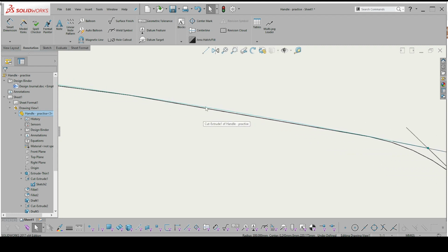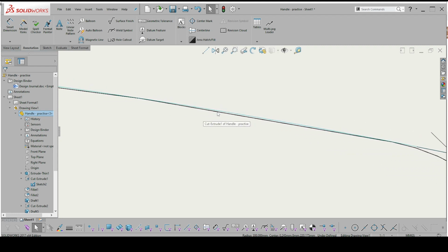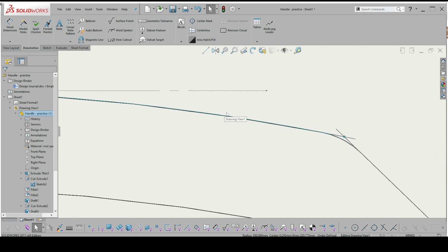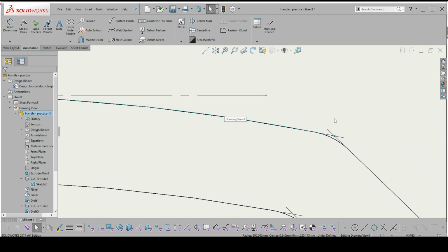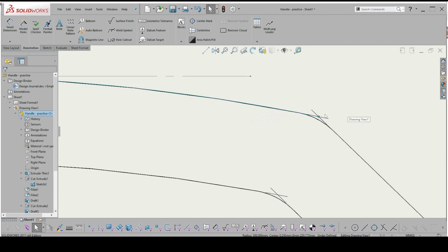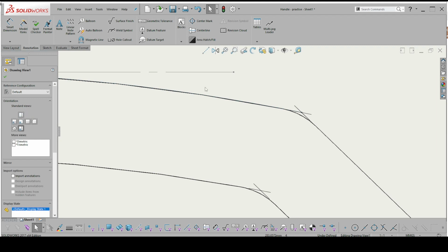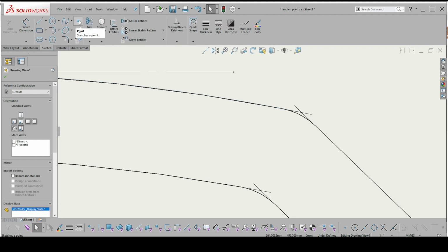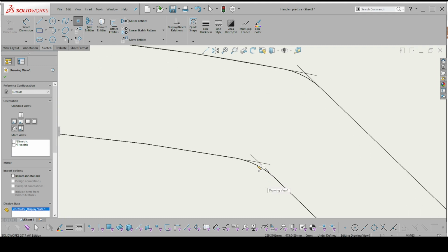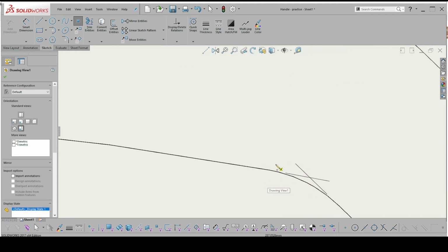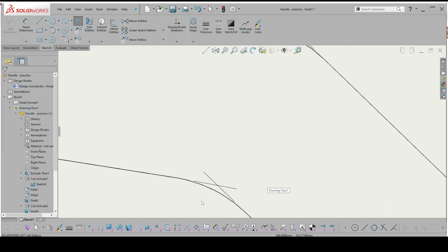That is the sketch, and you can see the sketch varies a little bit in this case from this top line. That's going to become important. I'll show you in a second why. But what you can do here is, if you can't find these virtual sharps easily enough, then with the sketch showing, go across to your points and just put in the points where the sketch shows. Sorry, it's not showing at the moment.